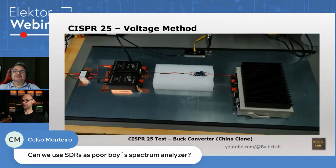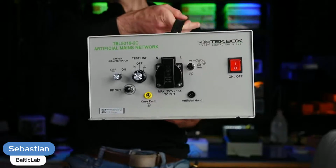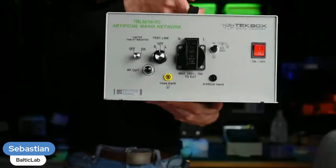For instance, here we use LISNs to have a very strict controlled impedance. The real world doesn't work that way. The same with your wall outlets. There are LISNs that emulate your wall outlet, like this huge thing. Let me make that full screen. Yes, so nice. That is a LISN that simulates the standardized line impedance for wall outlets. Obviously, this thing is a lot bigger and heavier because it can handle 16 amps.